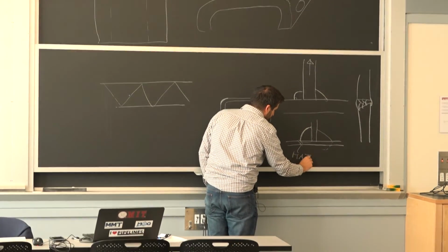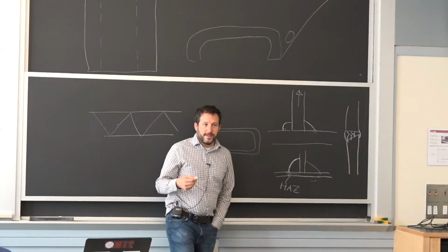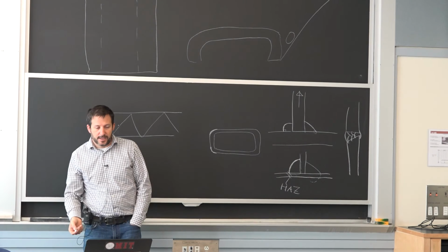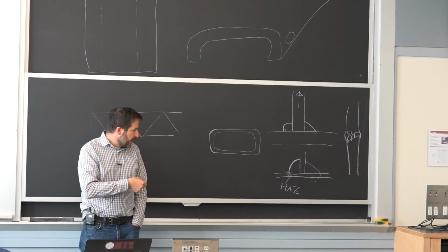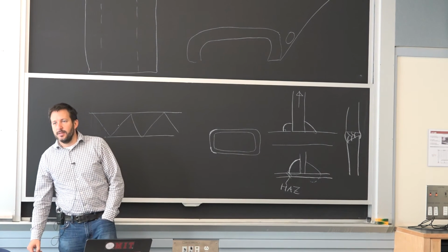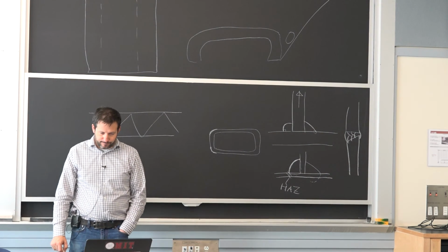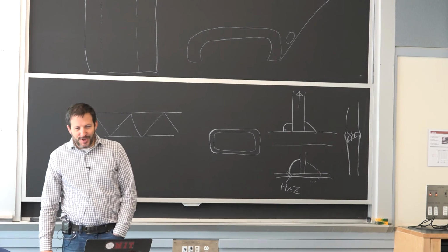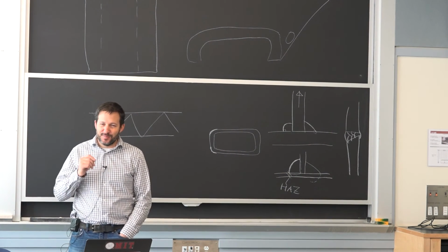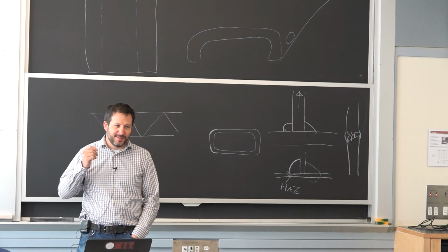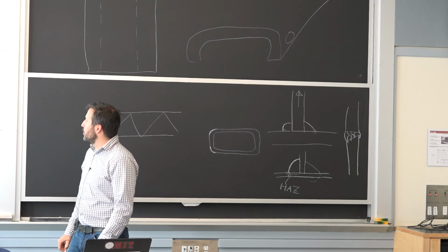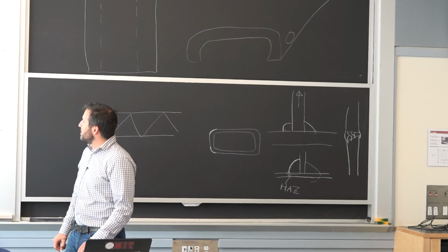That material went through essentially a heat treatment. It was heated up and cooled down fast. And a lot of times it will be in residual tension, and it's a place where the cracks can start. So I hope that by my last lecture, when I emphasized why welding was great, that it was allowing you to do things fast, doesn't get overly diminished by this discussion.